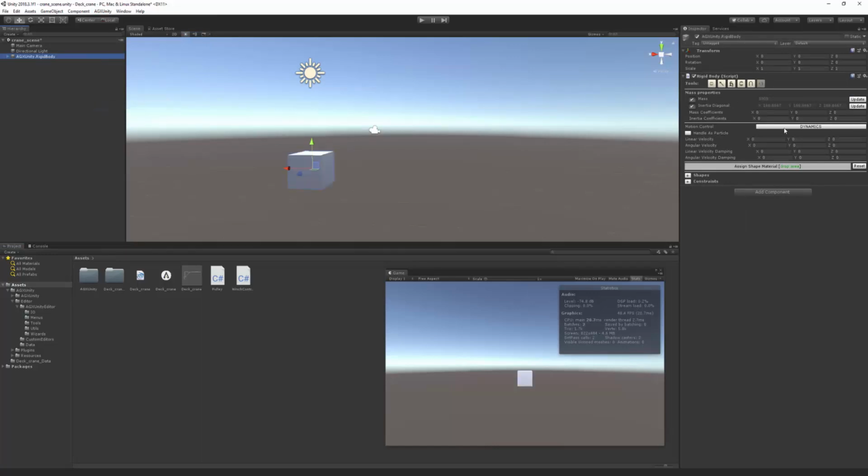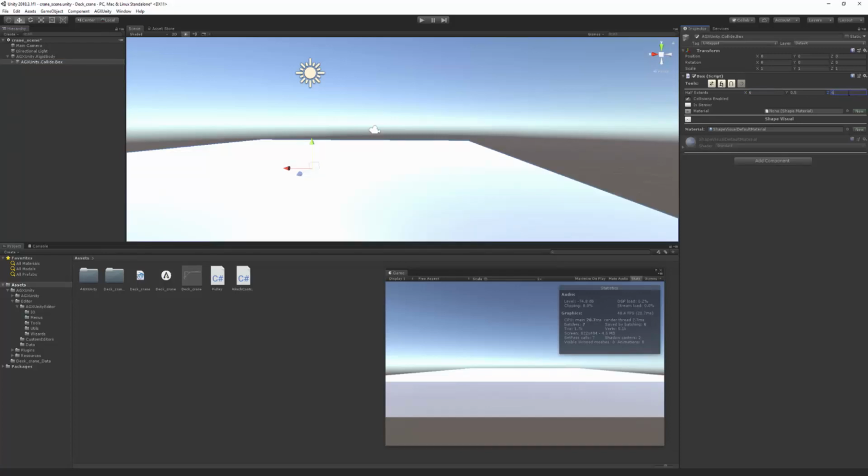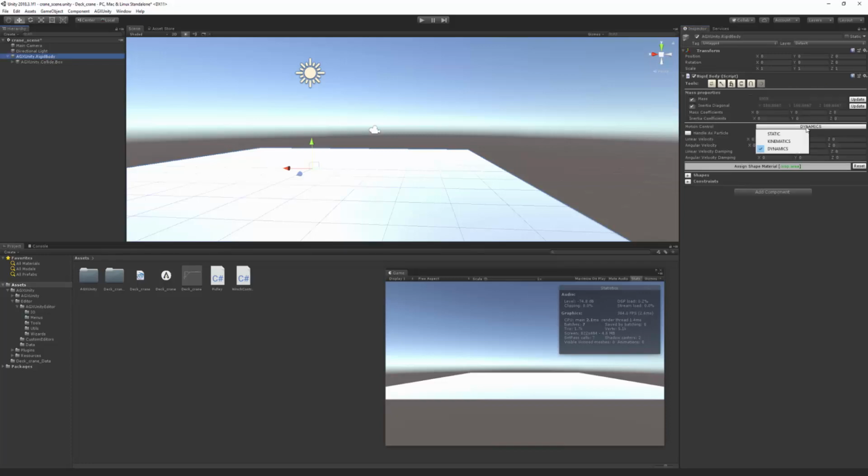When that is done, we are also going to create a ground plane, which is a rigid body, a box. So we can specify the size of that box by entering the half extents. So it will be 12 meters times 12 meters times 2 decimeters in height. We also want that to be static, so it doesn't fall down. So now we have a ground onto which we will model everything else.